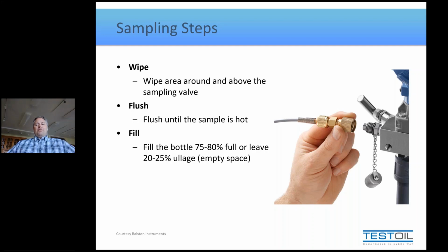So wipe it, flush it, fill it, but not quite all the way. Once you've got it full, cap it. Close the bottle before any external contamination can get in. And if you have not already, this is the best time to label the sample.